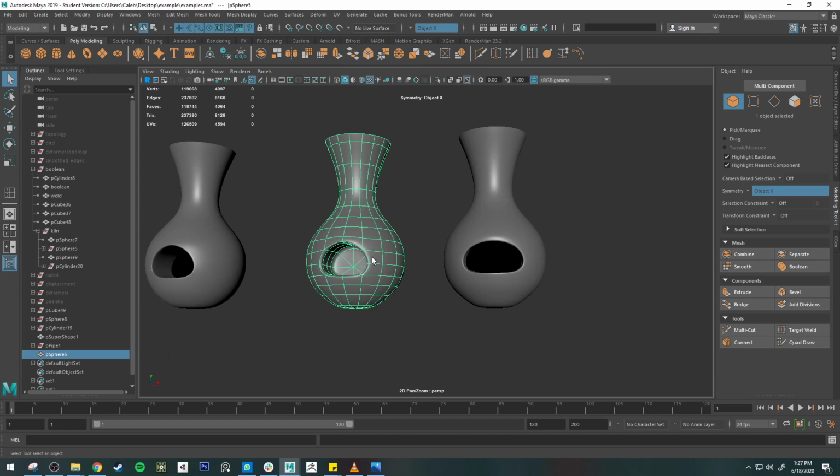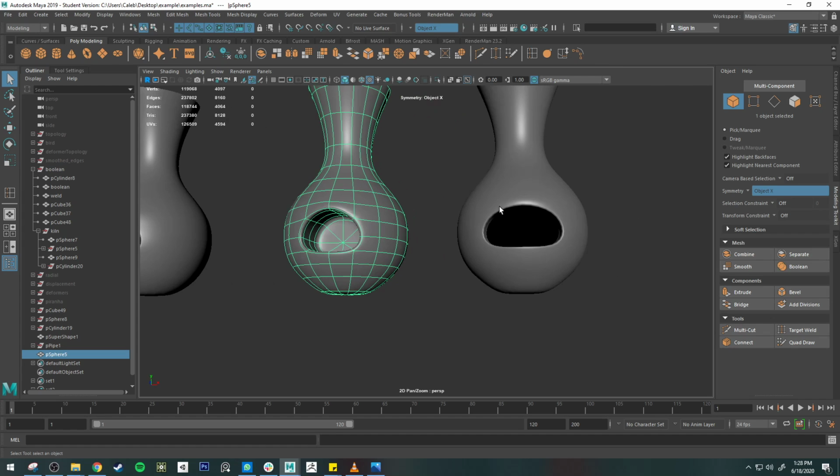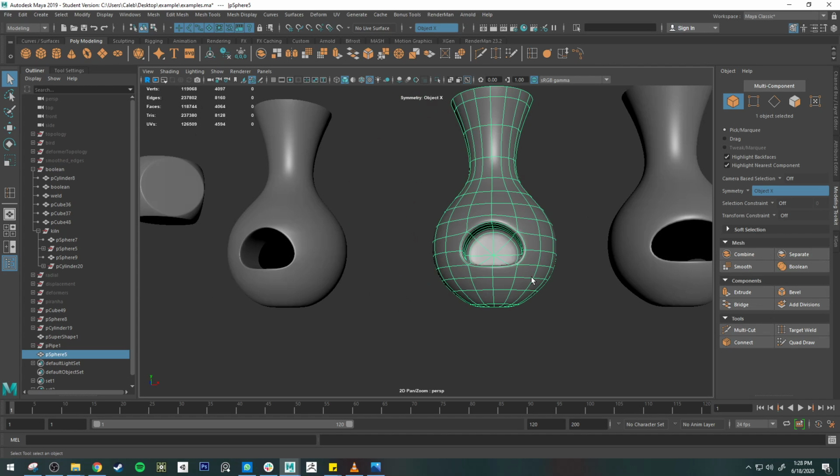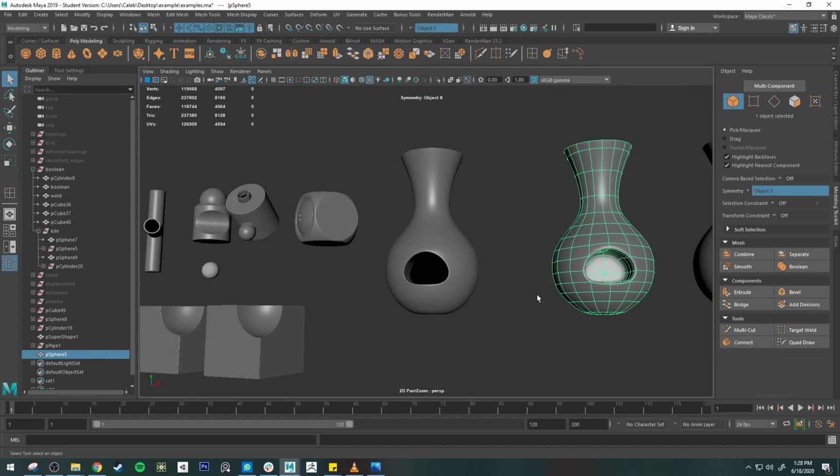What's probably easier about this one right here is that I can get that really custom shape out of that other object, especially if it's like a really smooth curved object that's kind of complicated or it would be too hard to cut out a specific shape, right? So we looked at how we could just cut onto the shape and create a hole, or we can use a Boolean to cut in the shape, or we could just use extrusion to push in and then pull vertices around to get the shape.